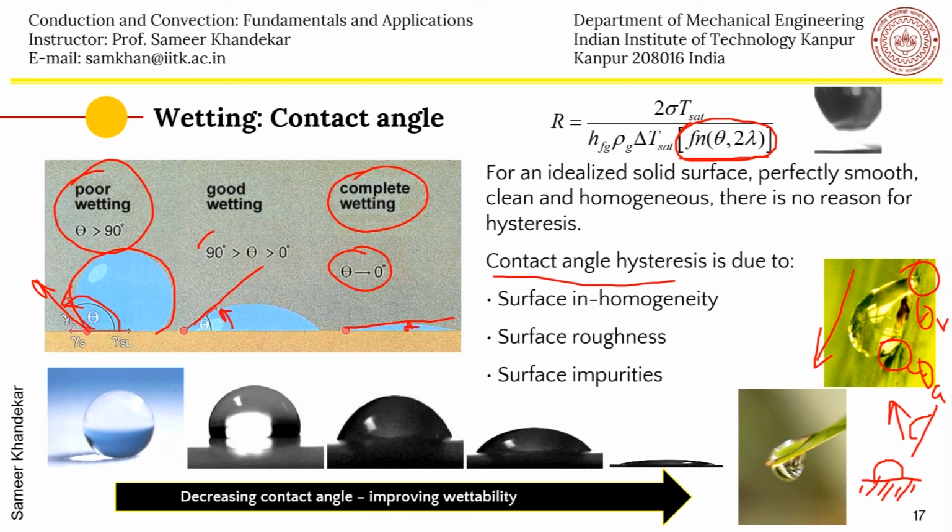Such hysteresis also plays a role in bubble growth or in pool boiling applications, and usually this is very complex. It is not so easy to have an analytical expression for this function, but researchers have found out the effect of wettability on pool boiling and how nucleation sites get affected by wetting and non-wetting fluids. This particular hysteresis can also be measured by an experiment which is shown here.